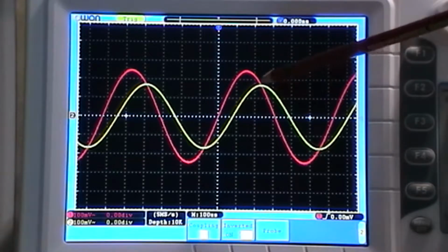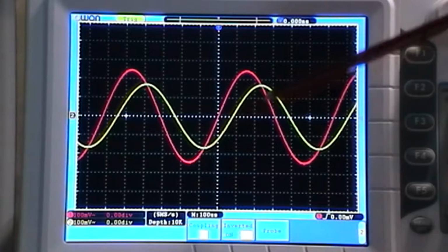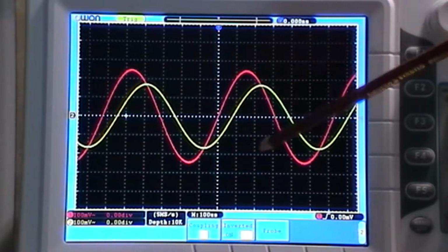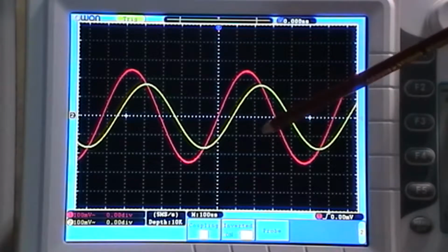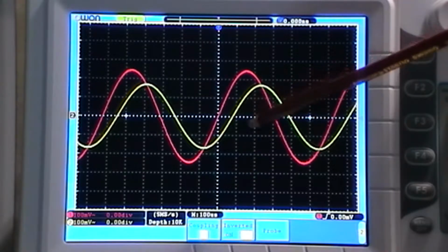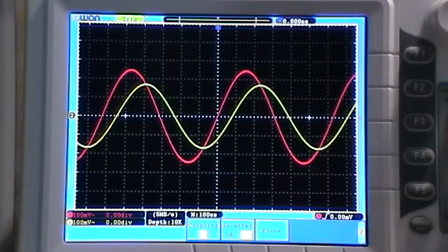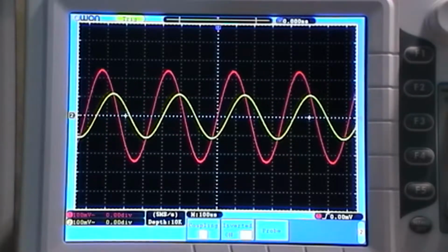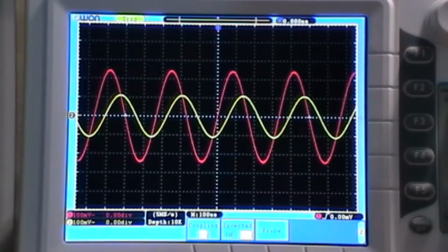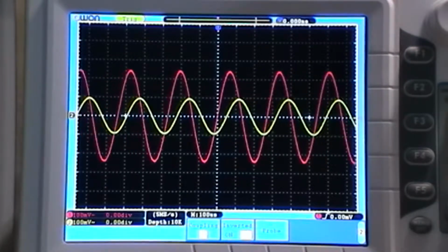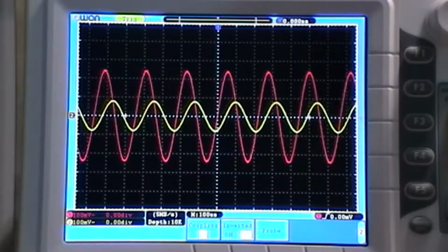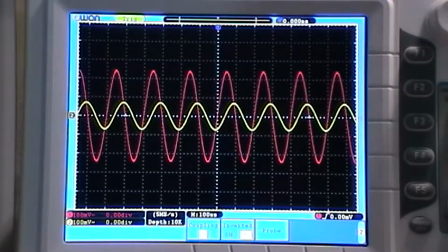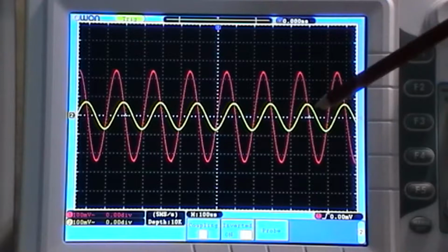It's a very simple one, but I'm not looking at that at the moment. I'm just looking at the fact that as I have different capacitors in there, I'm going to have a different frequency at which it's going to be attenuating. But obviously if I turn that up, I'm now at 3 kilohertz. We're really starting to lose that signal. We crank that all the way up to say 5 kilohertz. It's really heavily attenuated that signal, so basically I'm only getting out the lower signals.